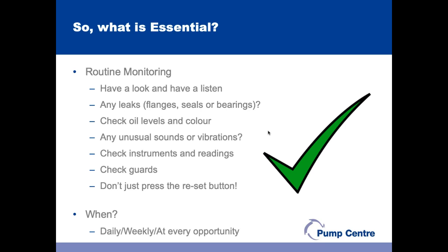What's the colour of the oil? Are there any unusual sounds or vibrations coming from the pumps? What do the instruments say? What's the ammeter saying? Anything that the instruments are saying that's different to normal? Do the guards look okay? Are the guards still fastened down, giving protection to people working around the equipment?